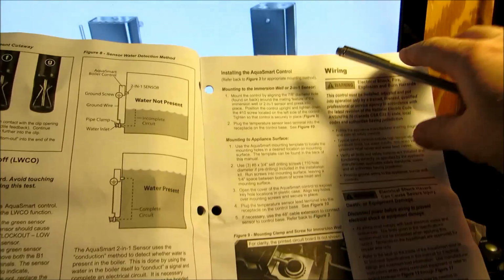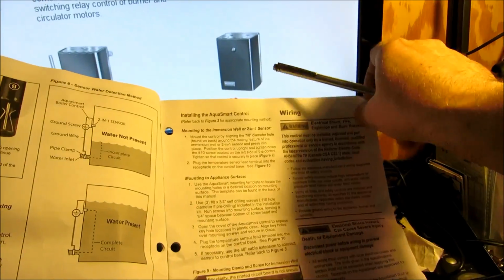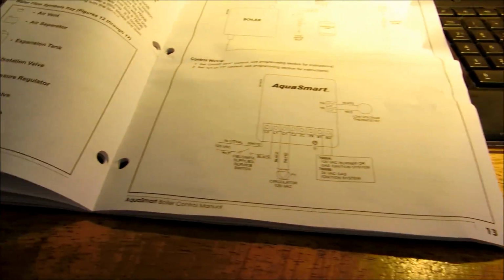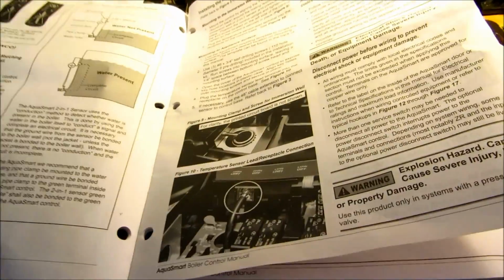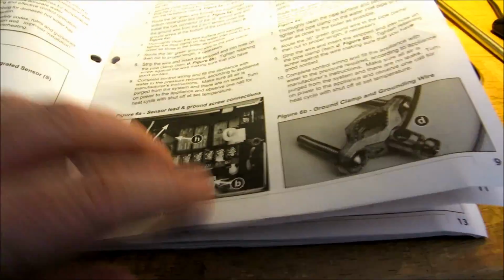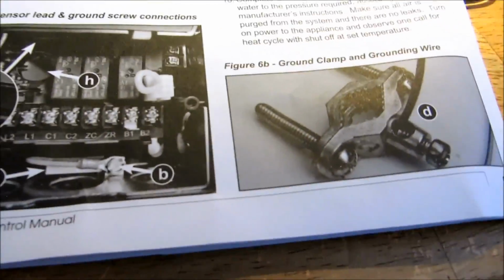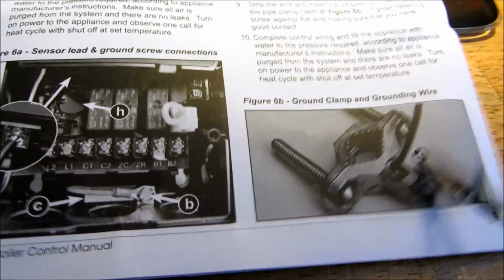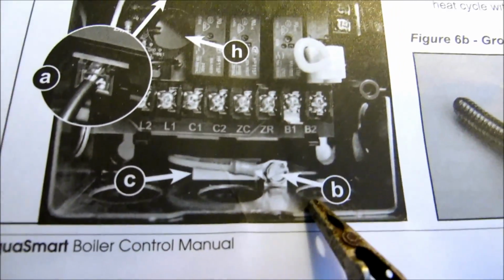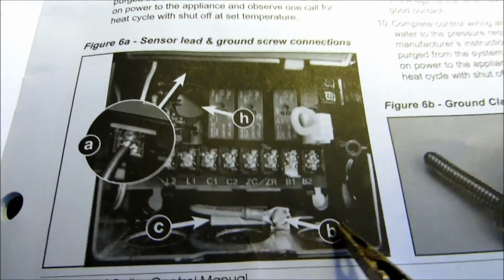And they say on these controls you want to add an extra ground to them, because the ground's a problem on some of these. I've had some problems with these controls. And actually the well is plastic, it's not even brass. Right here. They say you want to add this extra ground clamp, and that goes over to B, I believe. The ground on this control is B. They say to put that extra ground clamp.